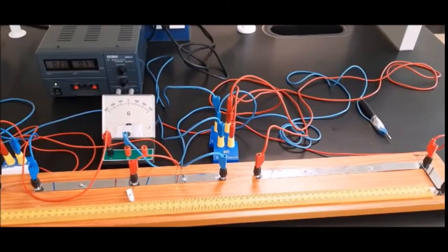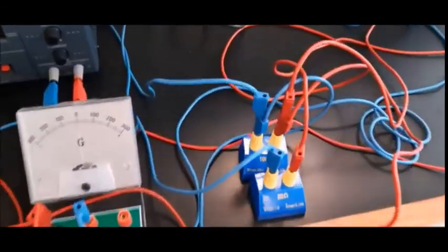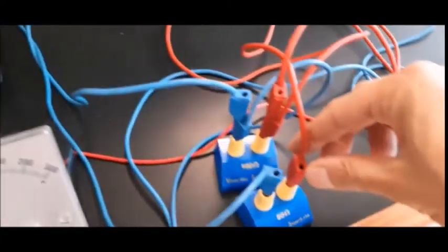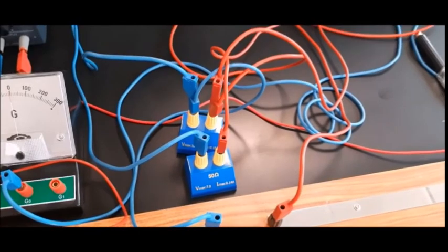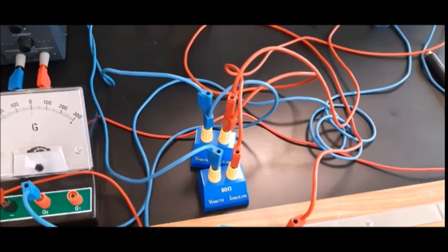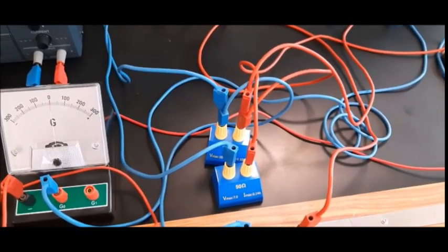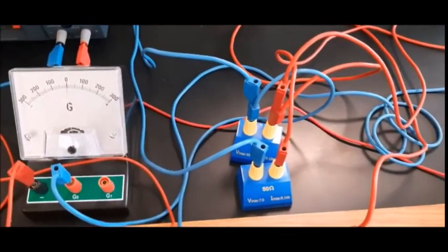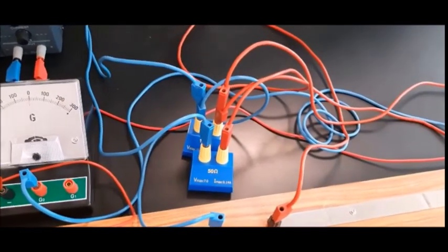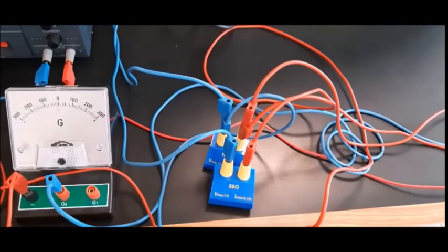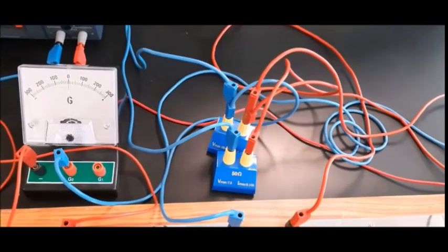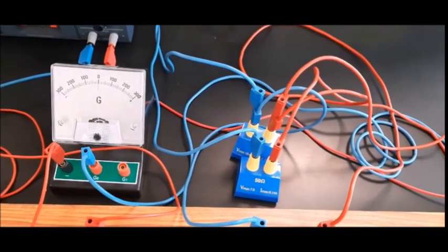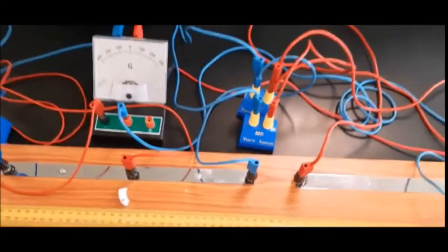Now, as a fourth reading, I'm using the same two resistors, the 50 and the 100, but I'm connecting the two resistors now in parallel. And when they are connected in parallel, according to the formula we know for the resistors connected in parallel, this represents a resistance of 33 ohms. So the resistance is now 33 ohms, and I will try to find the zero location.